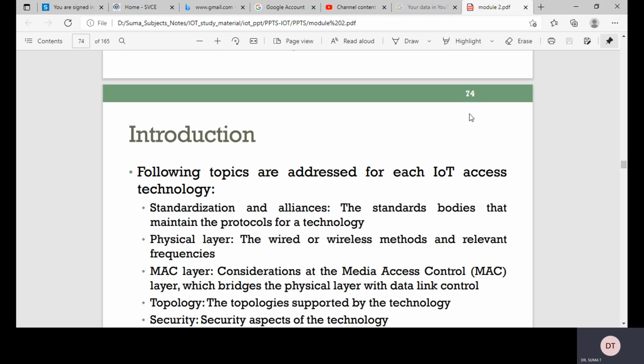Most low power wide area technologies offer small payload sizes. These small payload sizes are defined to cope with the low data rate, time over the air, and duty cycle requirements of IoT nodes and sensors. For example, payloads may be as little as 19 bytes using low power wide area network technologies, or up to 250 bytes, depending on the adaptive data rate. While this does not preclude the use of IPv6, as in some of the endpoint implementations.